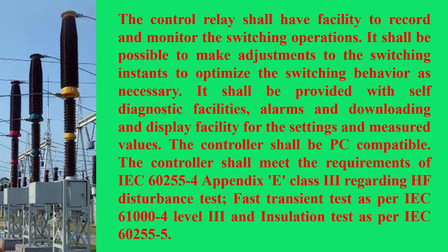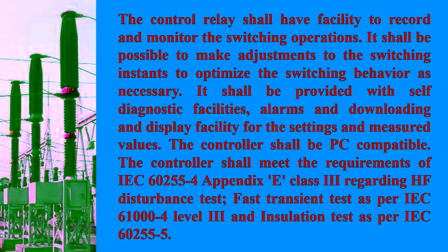The controller shall meet the requirements of IEC 60255-4 Appendix E Class 3 regarding HF disturbance test, fast transient test as per IEC 61000-4 Level 3, and insulation test as per IEC 60255-5.